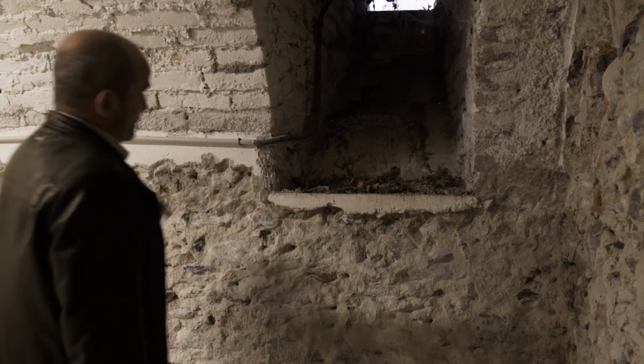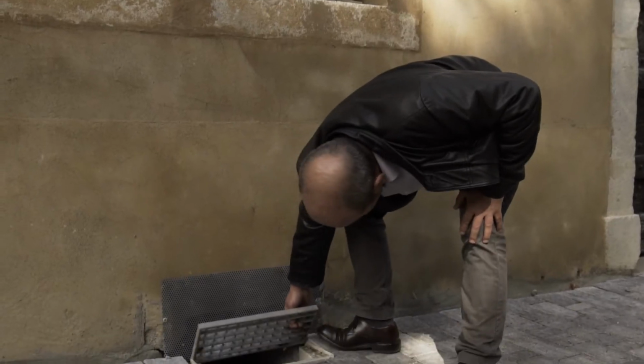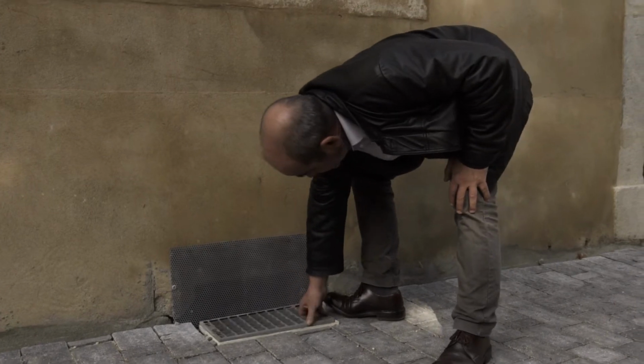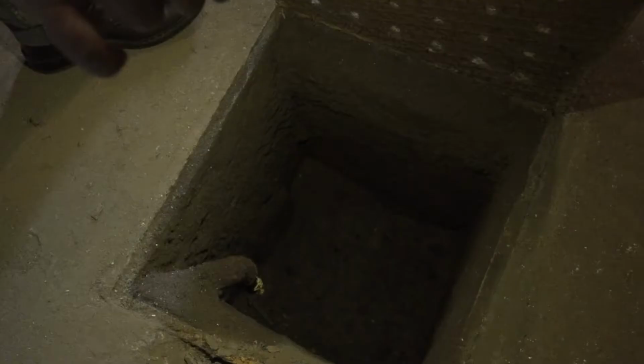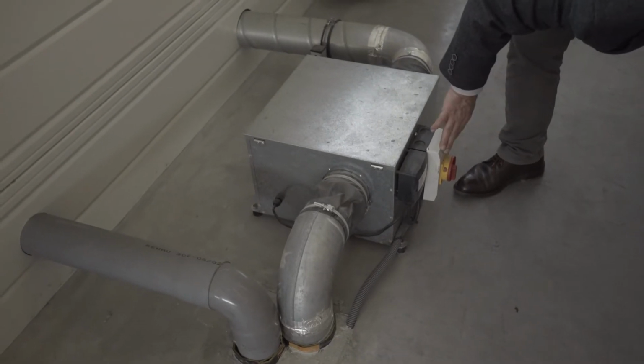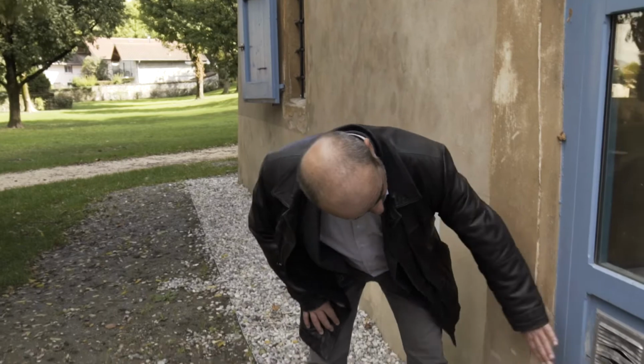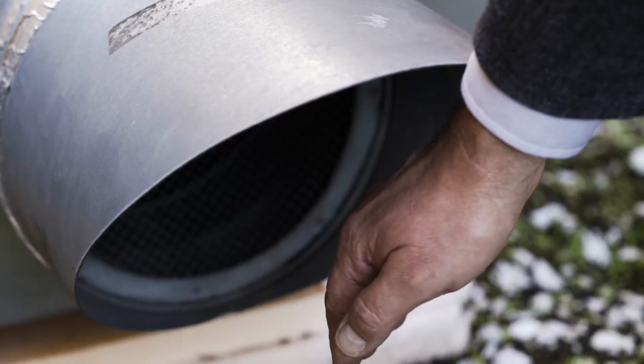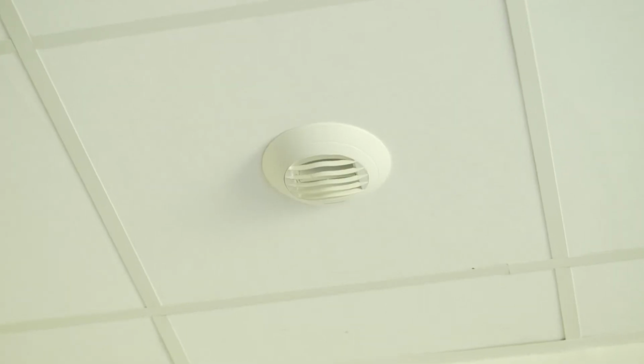We will also look at the level of ventilation in these basements. An identification of the different components that allow the ventilation of these volumes will be conducted. Windows, skylights, hatches, openings, air inlets, etc. In the same way, a very important point is to be able to evaluate the level of ventilation of the occupied spaces. Here again, this means identifying the different components that allow this ventilation. These can be ventilation grids, air inlets, extract units. And it will be very important to check the correct running and dimensioning of the entire existing ventilation system.